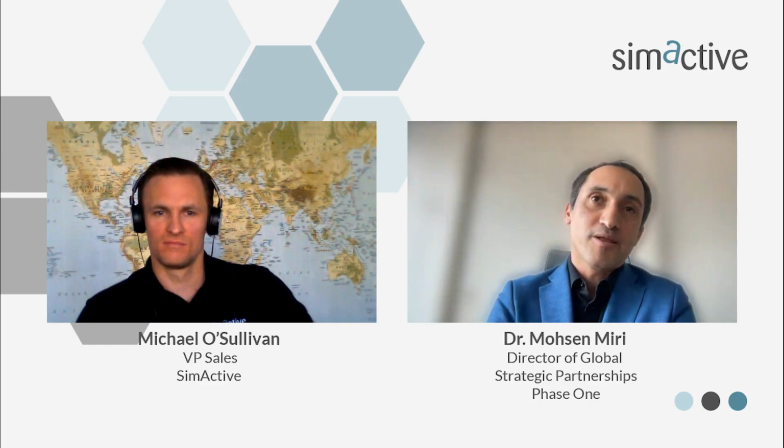During the planning, you are already planning the QC. You are planning the GCPs. Some of them would be reference points, some of them will be used as checkpoints. It's important that the accuracy of these GCPs should also be qualified, always having the report of the accuracy of the GCPs.